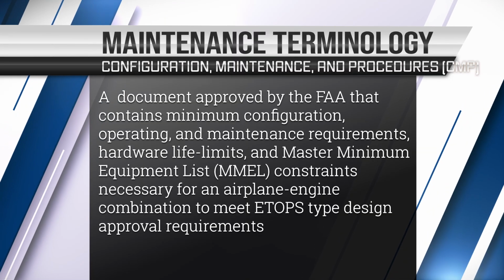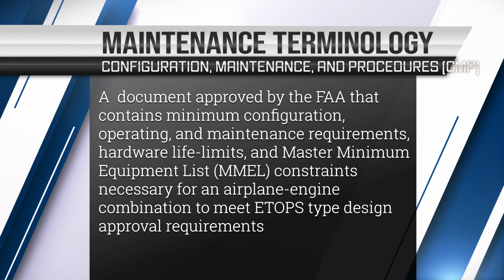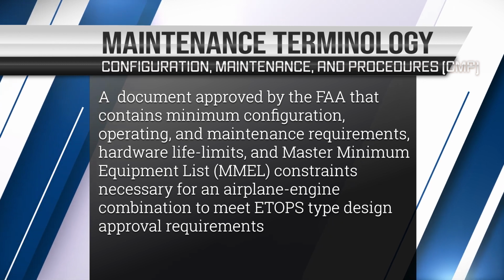It means a document approved by the FAA that contains minimum configuration, operating and maintenance requirements, hardware life limits, and most importantly, the Master Minimum Equipment List, or MMEL, frequently referred to as the MEL. Constraints necessary for an airplane combination to meet ETOPS type design approval requirements.